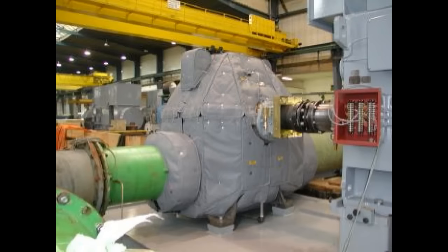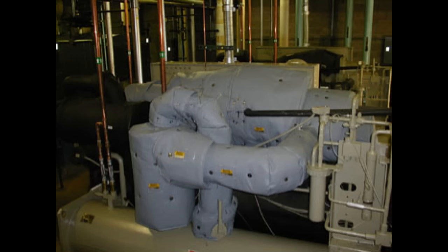I'm going to show you a few examples of blocking and absorbing noise at the source. If a piece of equipment, for instance, is liquid cooled or heat buildup is not an issue, we can often use something like this, which is a custom-made noise blanket. On the inside you'll usually find the mass-loaded vinyl, and then some absorptive material, quite often the acoustic fiberglass mat, sewed together. And we custom make those in panels, and then in installing them, they all tie together real tight.